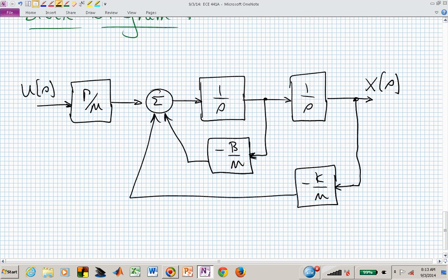And you could look at that in the time domain if you wanted to. Like I said, if I gave you a block diagram of a system and said, provide me the all-integrator block diagram, that would be pretty straightforward, I hope. You would simply erase the 1 over s in those blocks and replace it with an integral sign, and now you have the time domain block diagram, the all-integrator block diagram.